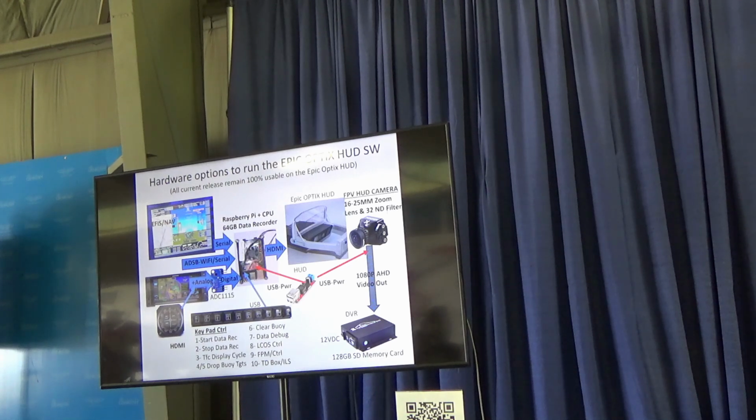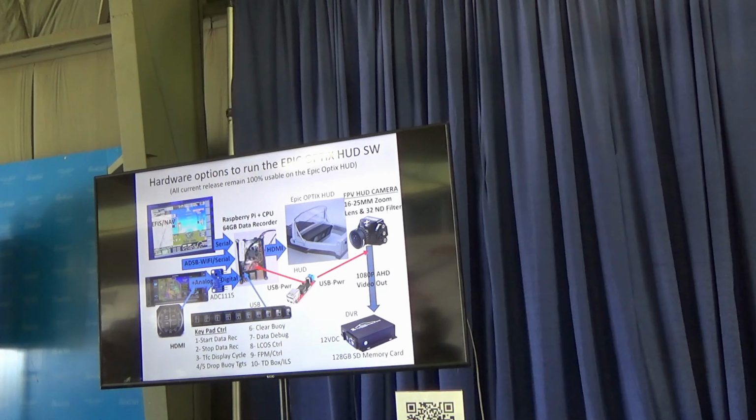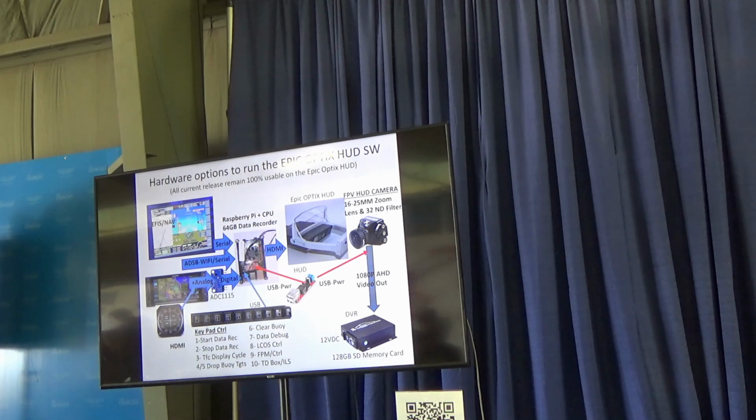in MGL, a lot of your nav data comes right out of the serial port. And the Garmin G3X, they don't output very much of anything when it comes to serial data out of their text stream. So what we developed was a little analog to digital chip. These are very, very small, cost about $12. You take your 150 millivolt needle output, horizontal and vertical, feed it into the analog chip, output the digital signal, feed it into the Raspberry Pi, bring it up in the software, and you have the same type of outputs you'd want for your vertical and lateral deviation. Works great. And then in the software you can call it up or not have it in there.